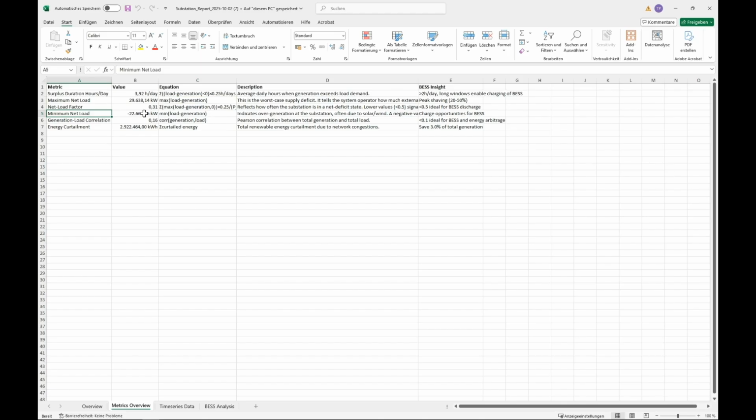On the contrary, there is an export reached in the last 12 months of 22.6 megawatt in total. This was the highest export at a certain point because the load consumption was very low at that point, and there was a lot of generation in this network area. This is important to remember here because this value is something we consider to think of what kind of PV utility plant we can still build. So this is, let's say, 23 megawatt.